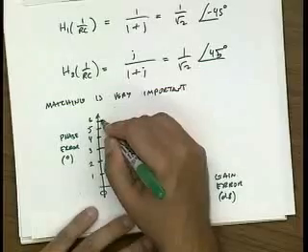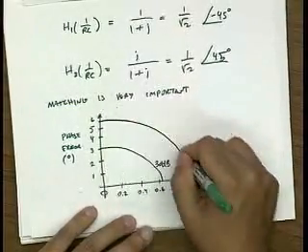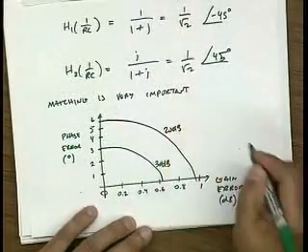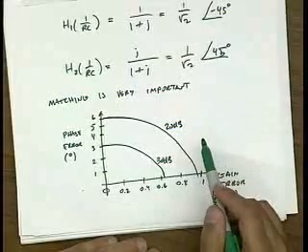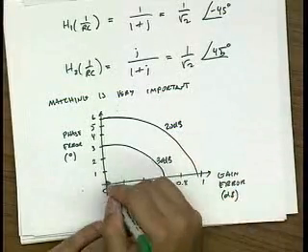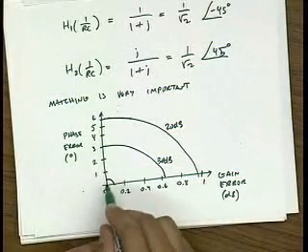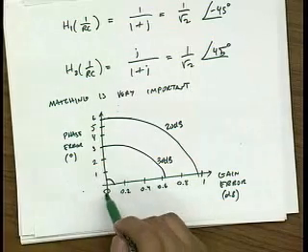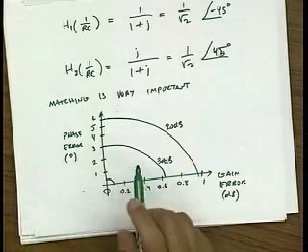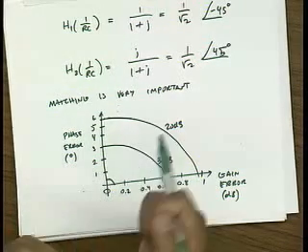Of course, as you go out more and more, so somewhere out here, this would be a 20 dB image rejection. The more gain error and phase error you have, of course, the less image rejection that you have. And if you want a lot of image rejection, you have to be over here, which requires very, very precise components. Now in real life, you'll never get that much precision. So the only way to get to, let's say, more than 40 dB of image rejection is some kind of calibration scheme. You need to actually tune your components to get that much image rejection.